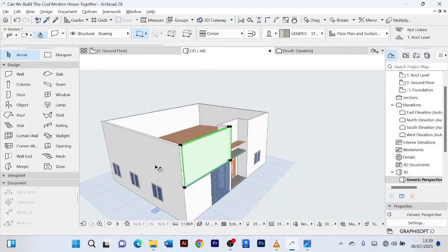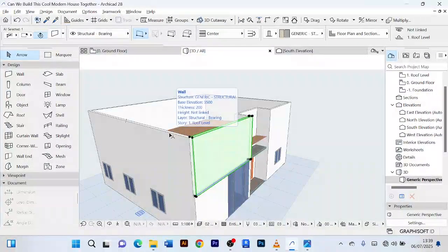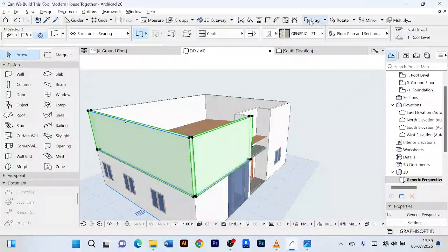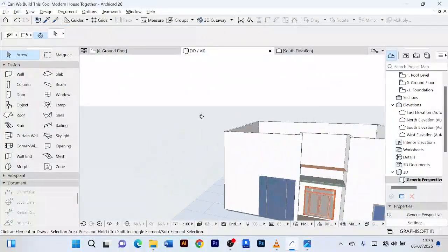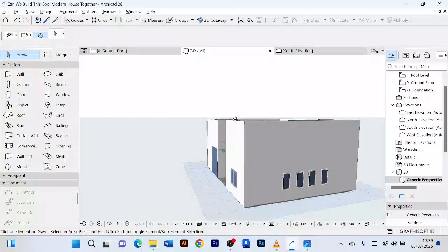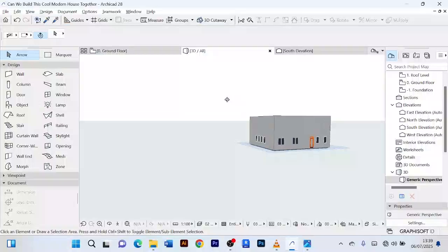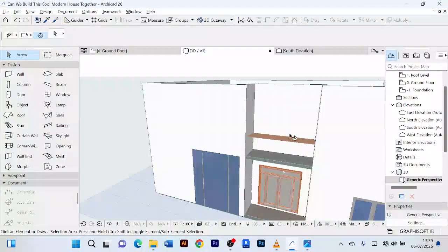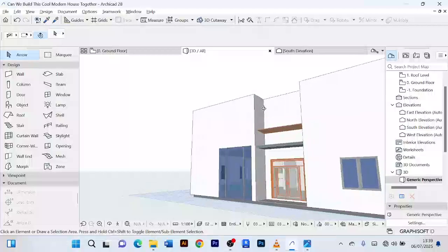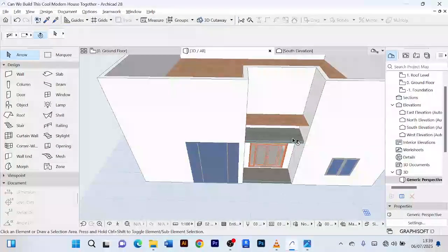Now we can select this, and you hold on shift. You come to this intersect, you intersect them so that they can align perfectly. You look for all those ones that need intersection, you intersect them like that. So now this is how we have hidden the roof. You can't see it, but still it is not what we want to achieve.